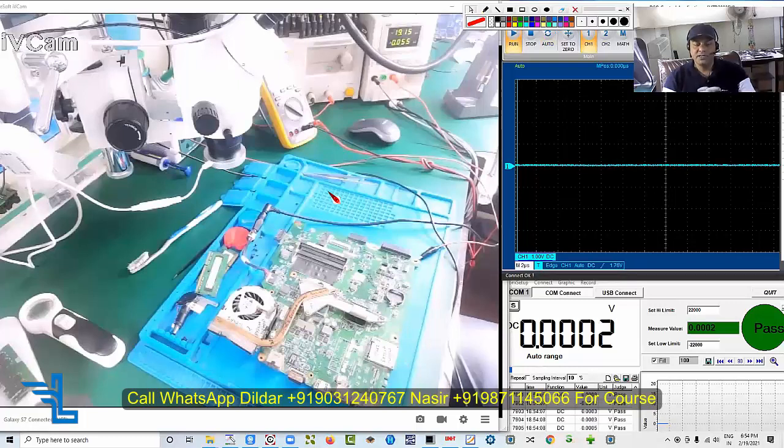My name is Nasir and I am again with the same case study which we left last week. The board part number is DV15CP, and I have demonstrated to you that the EC reset was having a glitch, and 3.3 and 5 volt were missing.